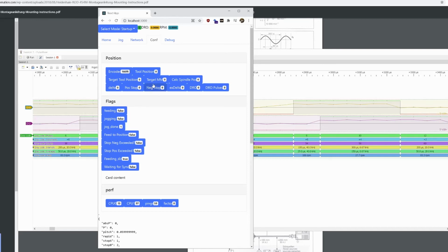So there is some small error in there. I'm not sure if the error is with the stepper or if the error is with the encoder processing on the ESP32 side. The ESP32 should be able to handle quite a high load. I think I calculated that at 800 RPM, it was going to be 192 kilohertz of updates.